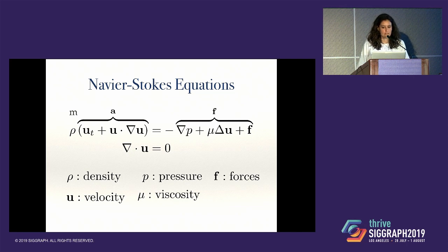Now, the rho there is representing our mass density. The quantity in parentheses is analogous to acceleration, or it actually is acceleration. And on the right-hand side are all the different forces that are acting in a fluid. And then we have this other equation, which is our incompressibility, which I'll mention. So here's density, our velocity. So the fluid moves at a certain velocity, and these are all the terms that depend on that. Pressure gradient, viscosity, and any other forces like gravity, perhaps sometimes surface tension can be put in here, or maybe interaction forces with other things.